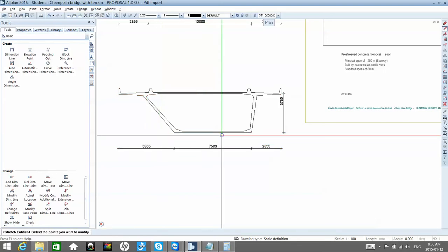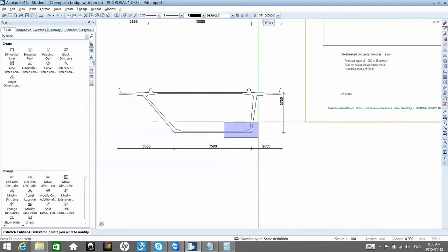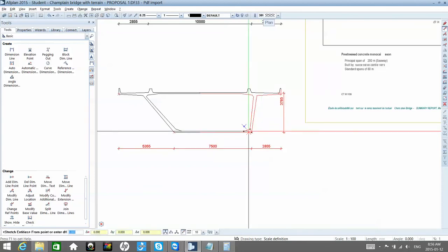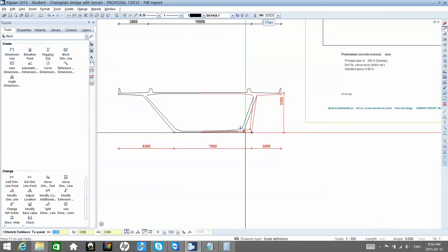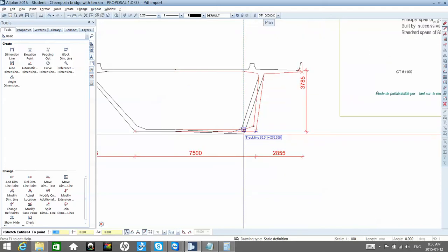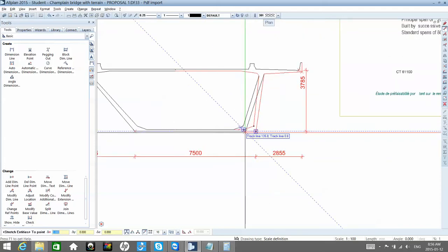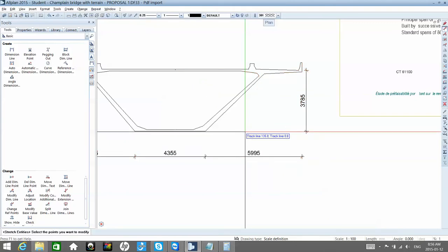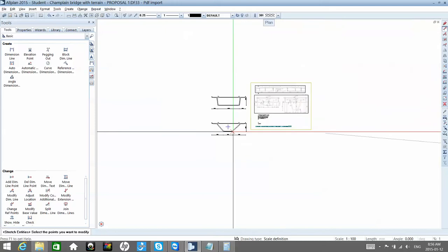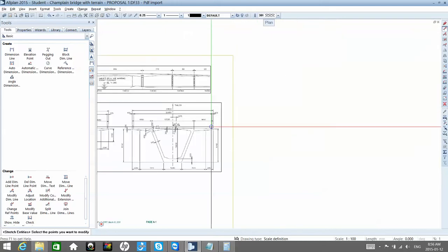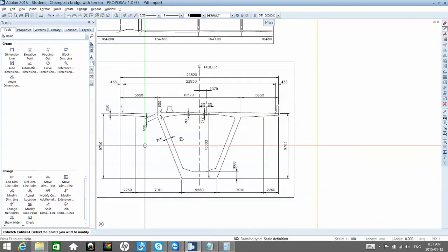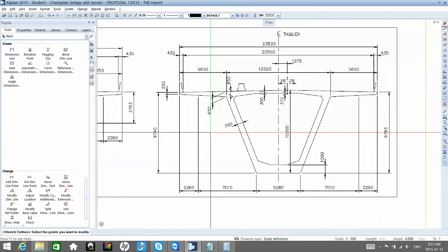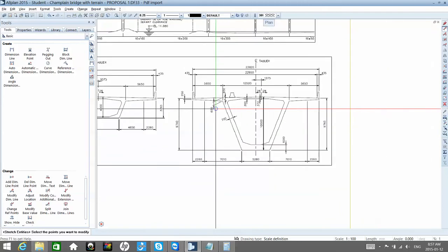If we try to create the second one, there's the risk that we may enter more points than in the first one, and then the bridge modeler wouldn't work, as it can't follow the points because it does the interpolation between the points we give it. Okay, and also let's modify the height. It was 3.7 and now it's 9.7, so it's 6 extra meters.